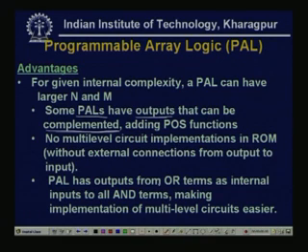PAL has outputs from OR terms as internal inputs to all AND terms, making implementation of multi-level circuits easier. So here it is possible to get multi-level circuits. It is a programmable AND, so we can take the worst case or exhaustive case, all possible minterms, and then implementation of multi-level circuits is easier by using PAL. But normally in PROM this type of connection cannot be done, because there it is a fixed AND and only a programmable OR.